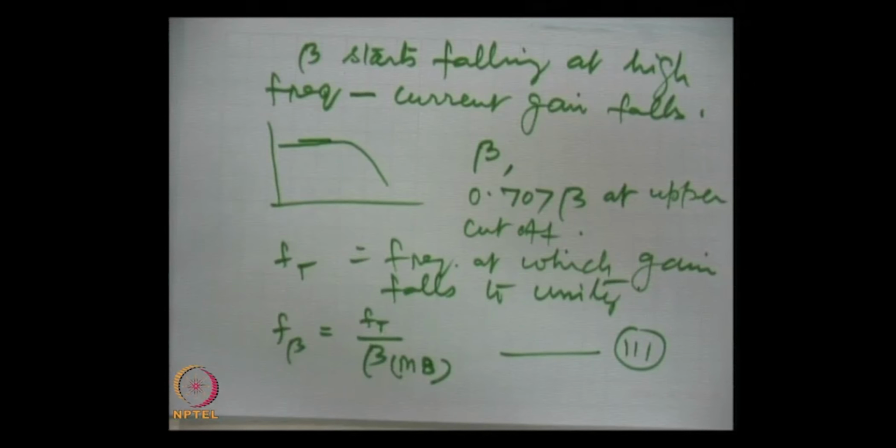At the input there were 3 cutoff frequencies arising from the 3 capacitors, 2 coupling capacitors C1 and C2 and 1 bypass capacitor, C_E, and whichever was the highest frequency will be responsible for giving F1. In this case, there are 3 frequencies arising from 3 different factors.